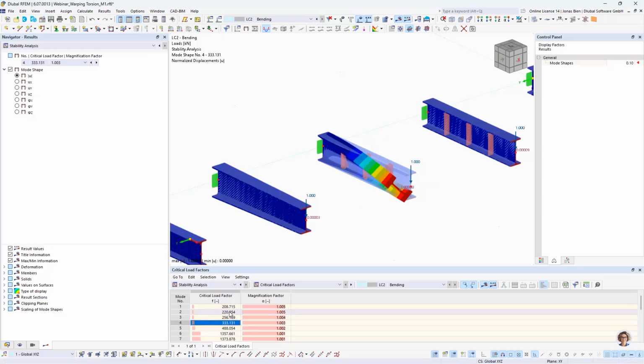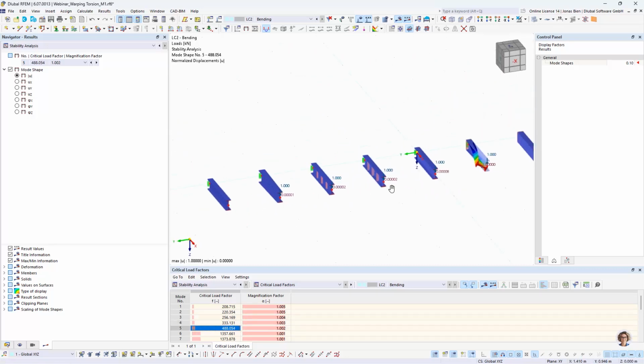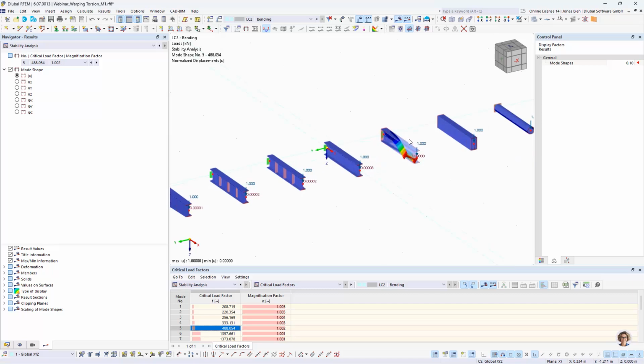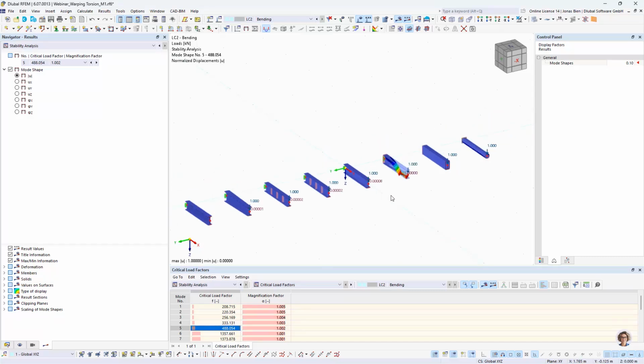Also here in the investigation of lateral torsional buckling, if we compare the flat stiffeners and the U-shaped stiffeners, it has a huge impact. And then we actually get the lateral torsional buckling of the cantilever where we applied this warping restraint at the end. So we can see that by doing so, our lateral torsional buckling capacity has more than doubled, from 210 to 490, more or less. So that's quite interesting to also see the effect on lateral torsional buckling.